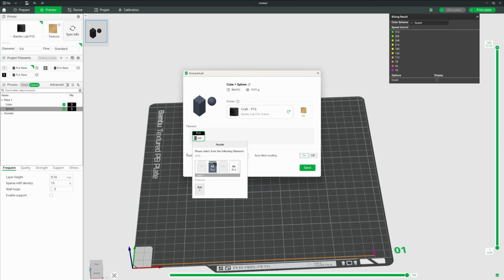If you want to change filaments and you have got an AMS module, you can pick whatever filaments you've got in that AMS module, just in case you've decided, oh, wait, hang on a minute, I didn't want to use that. I think it's grey blue. I wanted to print in white, so you pick white. And even though it's got the grey blue originally picked on the print bed, you can still change. So just a quick tip if you need to.